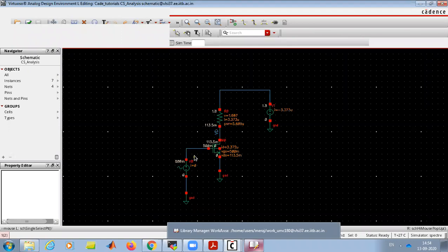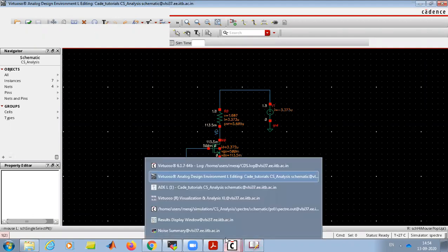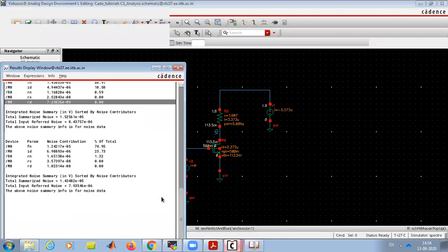The minimum potential is around 100 microvolts. So if it is 100 microvolts, your noise should be much less, around 10 microvolts. So these numbers are fine for our ECG measurement example.